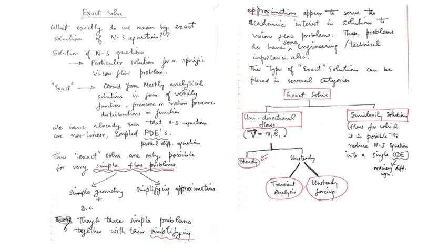But in general, any flow to qualify as a unidirectional flow must have this property, that the velocity field of any and every fluid particle in the flow for all times must be expressed as a component along one of the coordinate directions only. So it is not going to have all three components, but only one component. This is a unidirectional flow.